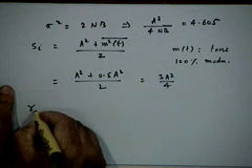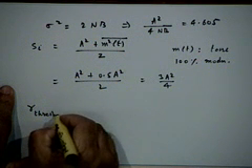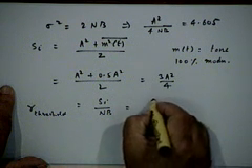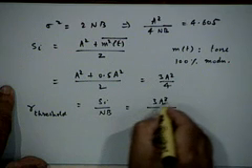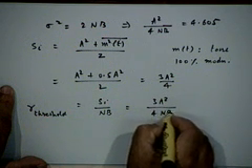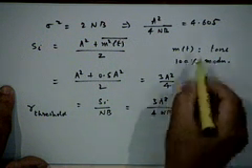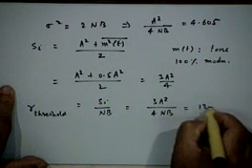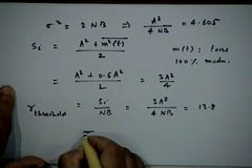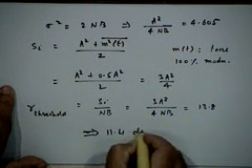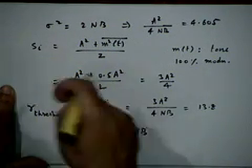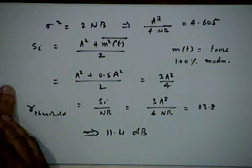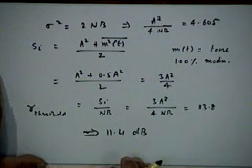So what is the value of gamma threshold now? That is SI by NB. SI is 3a square by 4, right, but the value of a square by 4 NB is 4.605, right. So this becomes 13.8, or in dBs this is 11.4 dBs, which is consistent with the figure I gave you a few minutes ago. I said approximately 10 dB, right. So this is typically how you will do the threshold SNR calculation.